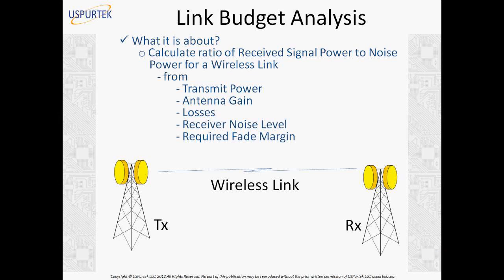Well, that is fine. Direct wave propagation is like line of sight. But direct waves within the troposphere get refracted too, so they work together. Tropospheric wave propagation helps us by extending our range of direct line of sight propagation. If you go back to some slides, yes, we are talking about greater than 30 megahertz. More than 30 megahertz we do have line of sight, but we do get help from troposphere refraction too, by extending our range when we are transmitting more than 30 megahertz.